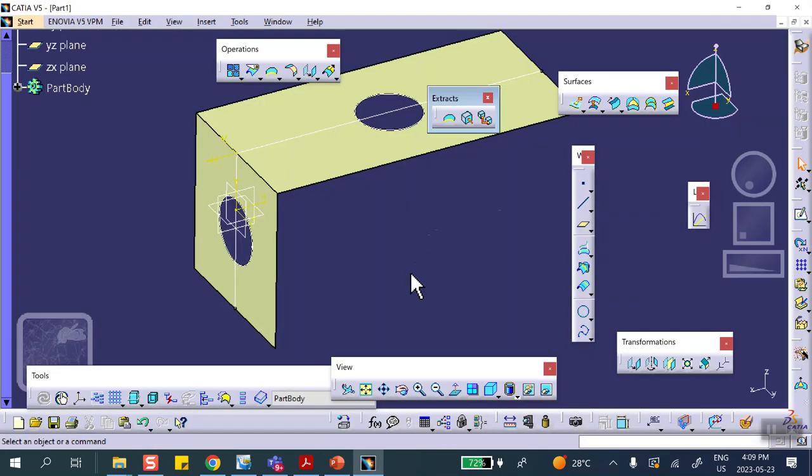A couple of comments that I have: there are many different ways of doing this surface. This is not the only one. The way I did it is I drew this L and extruded it. Because of that, when I mesh, the whole thing is going to get meshed, and there are no duplicate nodes here. Because of the way I did it, there's no need to join. If you want, you can join these two pieces, but there's absolutely no reason to do that.